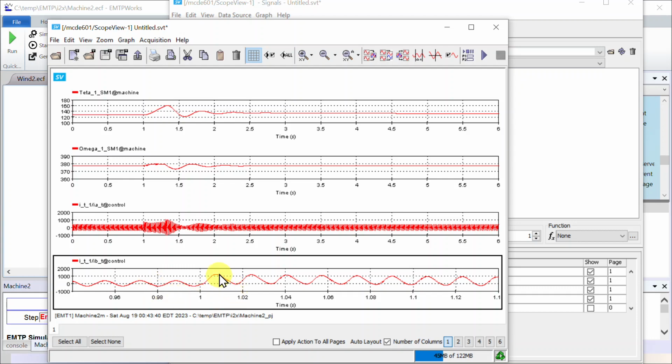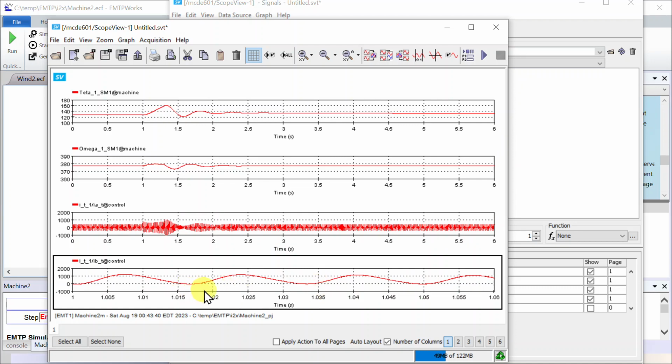You can see this is in amperes, but the DC offset is so high that it barely crosses zero. And this is a real concern when you're doing transient recovery voltages to look at the generator breakers, whether they're going to see a current zero or whether they can interrupt. And if you play with the resistances in the circuit, you could make it miss current zeros.